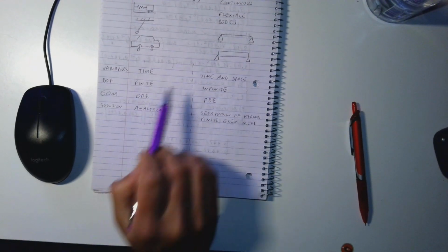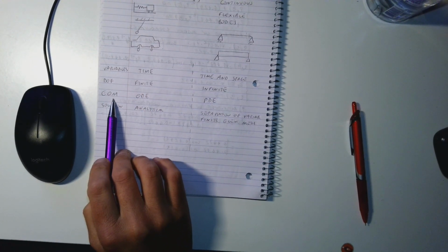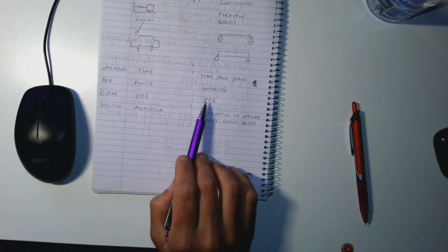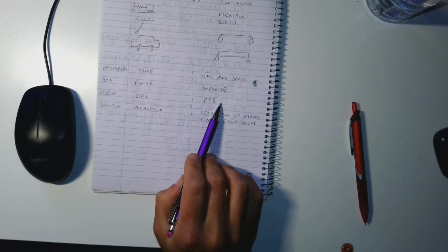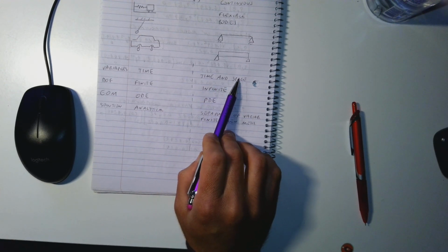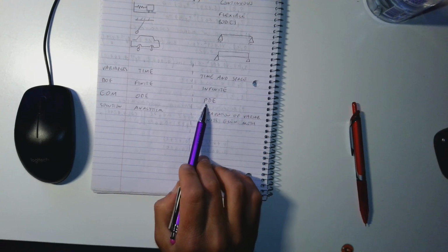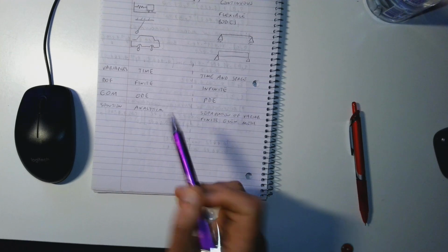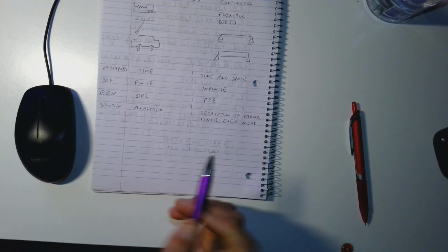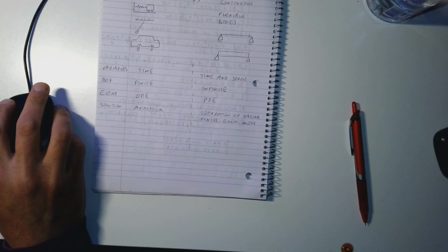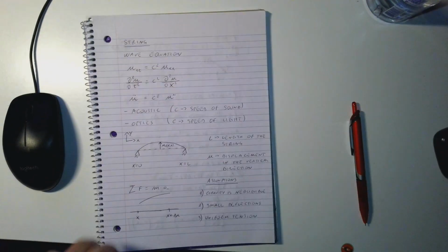Another consequence is that the equations of motion, instead of being ordinary differential equations, are partial differential equations. This is because instead of having only time as a variable, we have time and space. This is what makes the equations partial differential equations instead of ordinary differential equations. And then we will talk about also the solutions. We will see today how to solve actually the wave equation for a string. Any question about these differences?